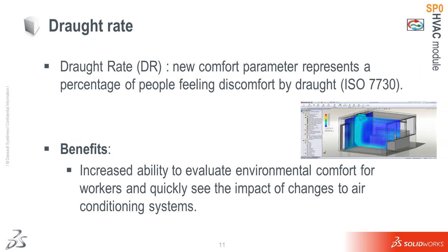during the design process. What is thermal comfort? It is defined in the ISO 7730 standard as being that condition of mind which expresses satisfaction with the thermal environment. However, thermal comfort is a subjective sensation. So the realistic aim is to create a thermal environment which satisfies the maximum possible percentage of people in a given room, taken as a group.